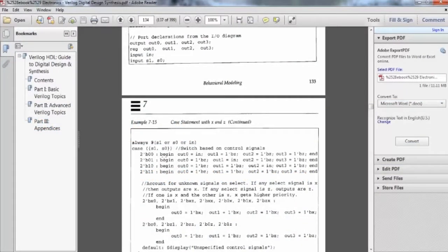Okay, so this is how the case statements are used for writing the code in behavioral languages. And you must have used the begin and end statement also. After always, we should use the begin too. So that's why you use begin, case, then alternative, then you again use the begin, then after that it will be end, and then another alternative, then begin the output, then after that it will go to end. So you can use it.